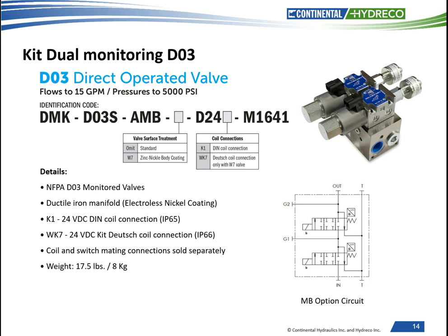In these valves, we also utilize a true 3-way valve spool design. This means that it is a fully balanced operation, resulting in higher flow rates and safer operation. Other circuits that I've seen utilize a 4-way spool design, which is an unbalanced design.